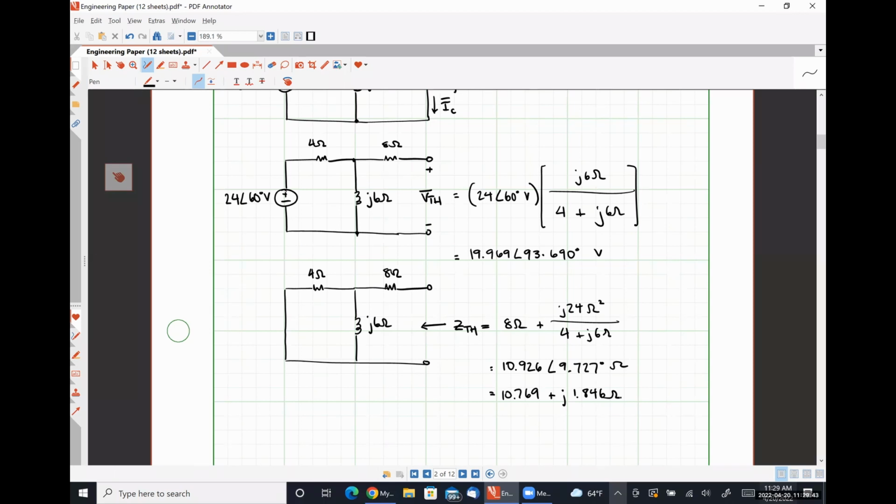Connor, I apologize for probably making you repeat yourself. Whenever you do the Thevenin impedance, you're just turning off all sources? Yes. So actually, that's not entirely true. All independent sources. So all independent phasor voltage sources and all independent phasor current sources. Any dependent sources would still have to be left in the circuit, and we would be required to use a test source method in order to determine the equivalent impedance directly.